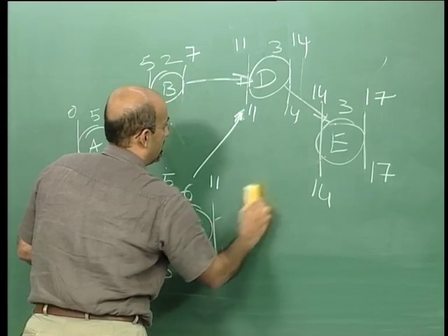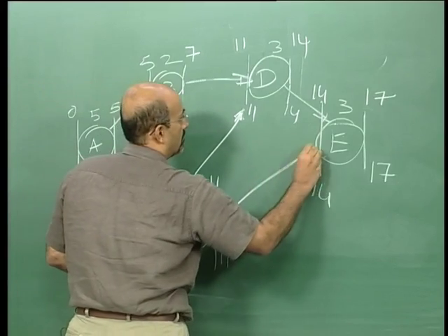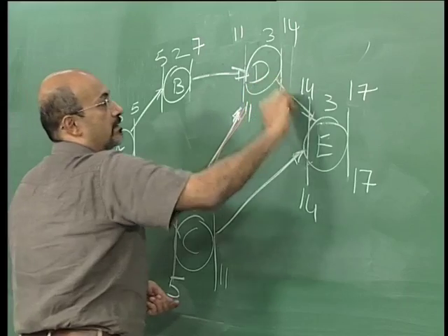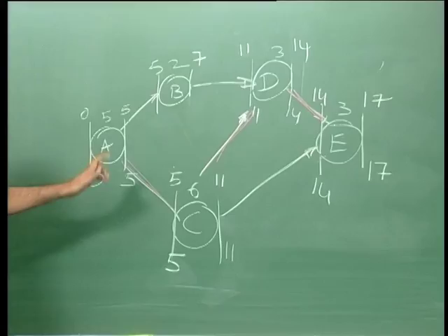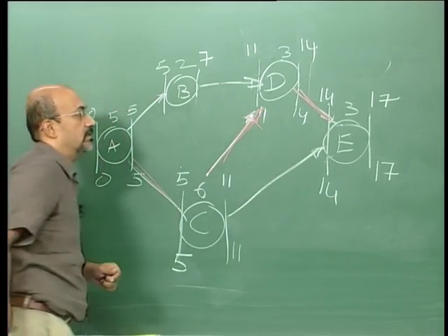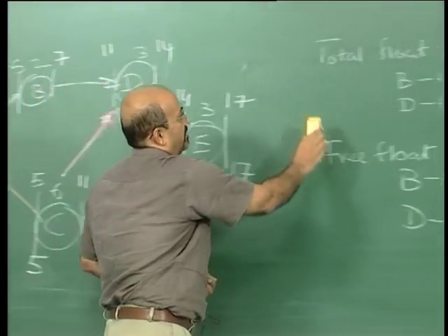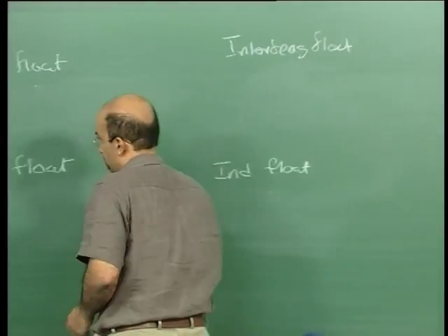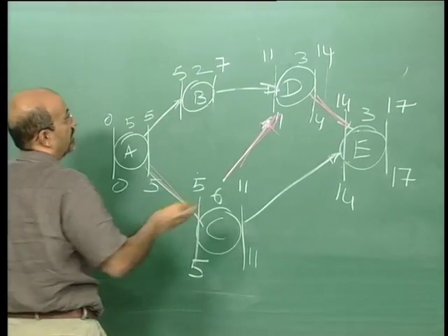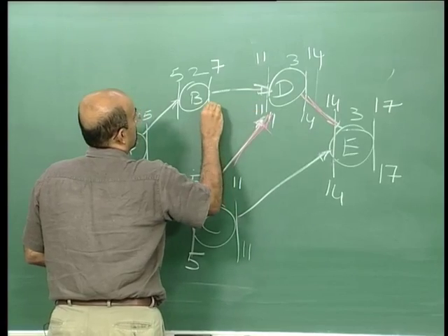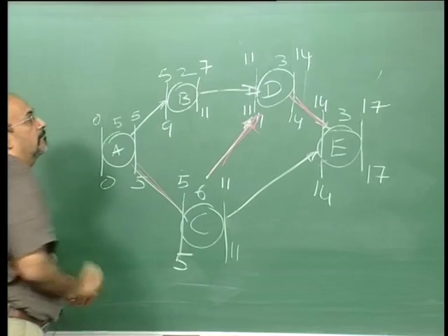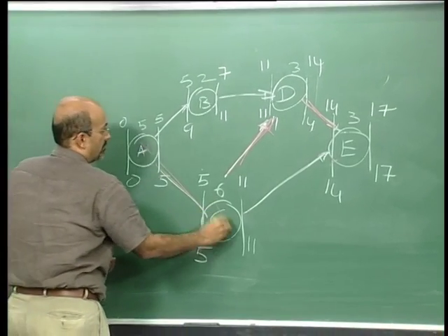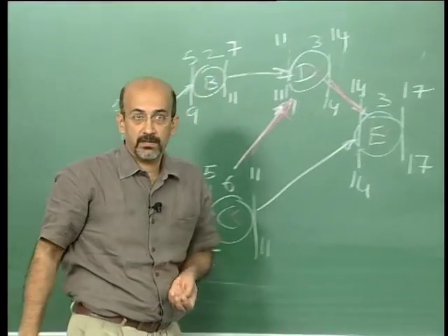So the critical path now changes. Where does it go through now? A, C, D and E. Because I changed the predecessor relationship here, now my critical path goes through this. Now let's see, it's the same example, slightly different relationships. Wait, I didn't finish this. So this goes back to 11 here. So now this goes to 11, 9. Again no floats on these because they are critical.